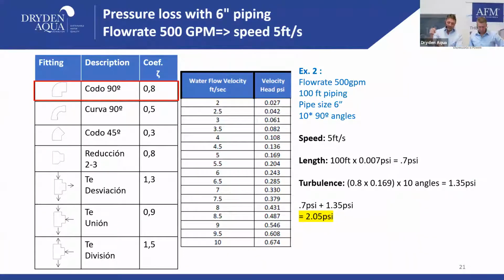Sean, let me add something. I just quickly did the math. If you work with the 4-inch, you will probably have to use a 7.5 kilowatt pump to overcome this resistance. With the 6-inch pipe, you can do it with 5.5 kilowatt. So that's 2 kilowatt of difference every hour, 24 hours, 365 days. It's really massive.